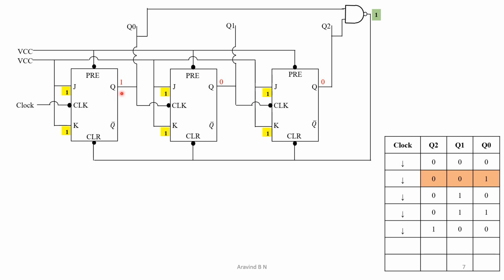Again the value has changed. Make an observation of what the input to the NAND gate is and what its output is. Now Q0 is 1, Q2 is 0. So 1 and 0 are the input to the NAND gate. And again from the truth table, output still remains as 1 only. And that is given to clear, so no problem to continue with the up count operation, right? So whenever the clock pulse is applied, it will move to the next value.